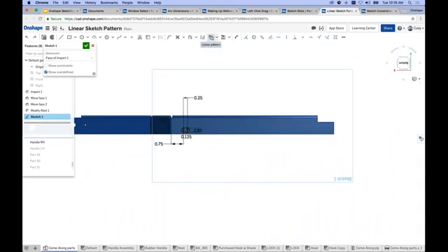So I'll select the linear pattern command from the toolbar, then window select the geometry I want to pattern. Now I have my pattern. Now, a few tips. By default, you'll see these arrows. If I want to change the direction of the pattern, I can left-click the arrow, and it will flip the direction of the pattern the other way. I can also grab that arrow and drag it to dynamically resize. So those are things I think many users, if you've used linear patterns, are aware of.